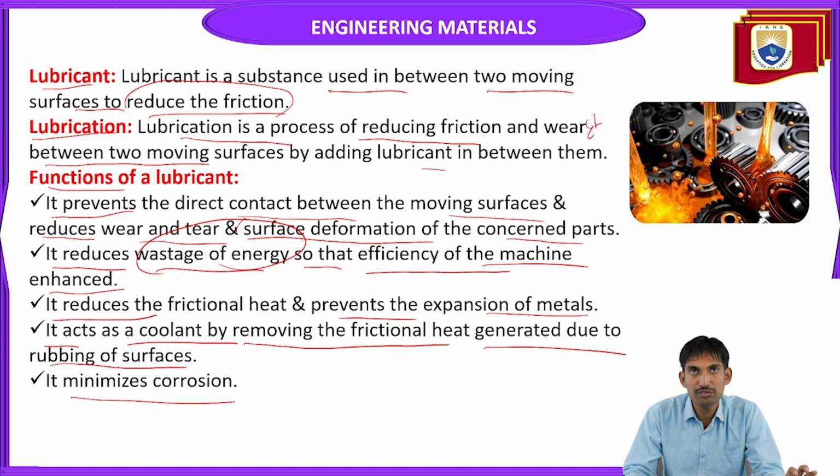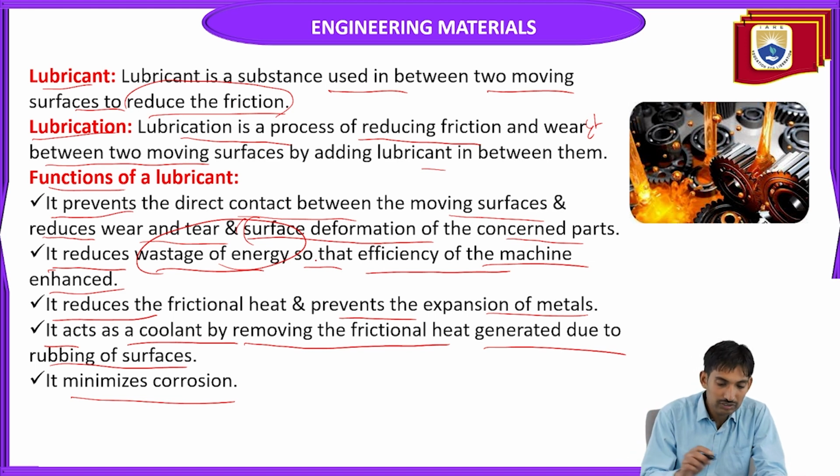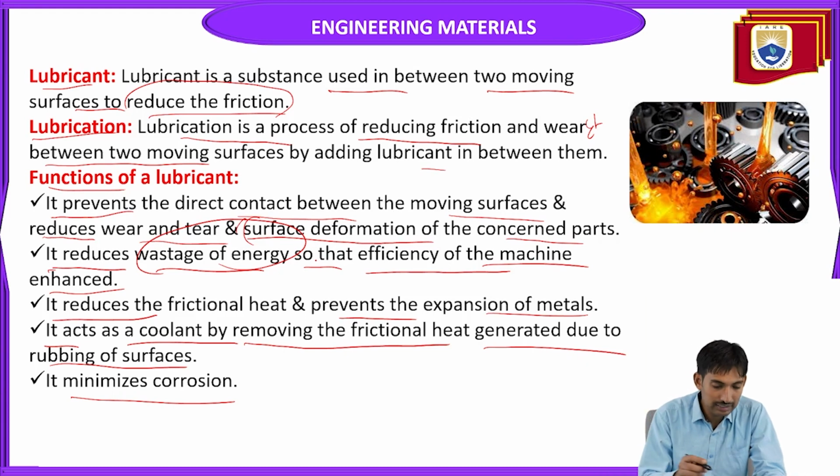What are the functions of lubricant? It prevents the direct contact between the two moving surfaces, reduces the wear and tear, and prevents the surface deformation of the concerned parts. It reduces the wastage of energy, so that the efficiency of the machine will increase.